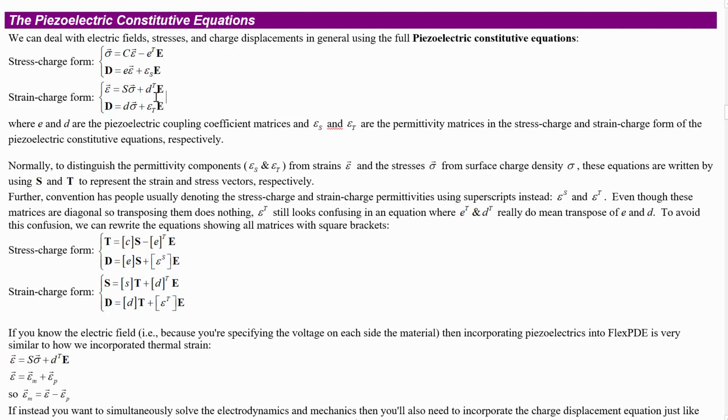That's what we had earlier. And then earlier as well, we also had that the electric displacement field D in a linear dielectric is epsilon S times E. I should say at this point that this doesn't fully cover what's going on with all piezoelectric materials, because some piezoelectric materials are even weirder in that they don't fully obey linear relationships here. We'll look at that a little bit later.